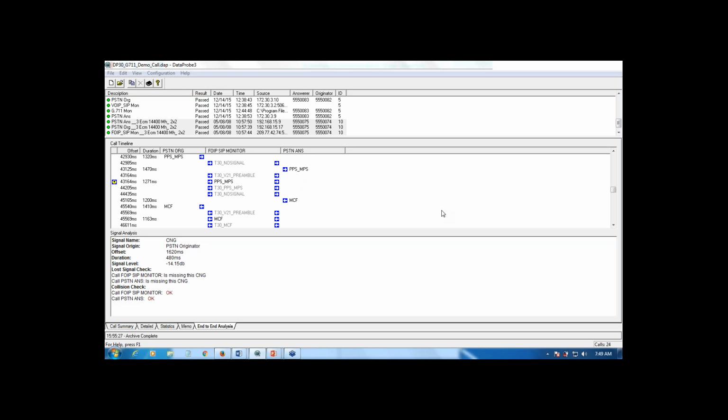It goes through, well, that looks pretty good. Let's change encoding from MH to MMR. Run it through, and all of a sudden the thing goes to pot. What happened there? And you find out that, oh, well, our gateway over here doesn't do a good job with turning MMR encoding back into a signal that the answering fax terminal can understand. So yes, it is hugely useful to use DataProbe with FaxLab.